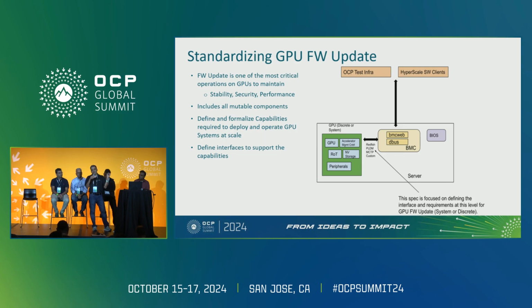with the 0.5 spec, you have a simple way, 3-click, I should not say click, 3 API orchestration method where you push the firmware bundle. A bundle is a composition of multiple firmware images onto an AMC or UBB baseboard, apply the bundle and activate the bundle. With that mechanism, with these 3 APIs, you can orchestrate firmware update of UBB in less than 10 minutes, and we have tested that at scale. And my friends here and in the crowd can attest to that as well.